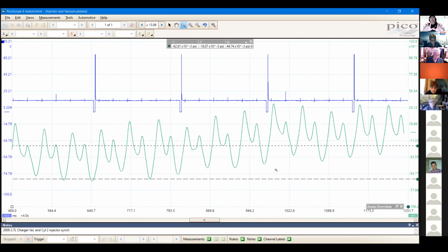And before you say it, and this is the last comment I'll leave you with, because I could talk about this for hours. Well, Adam, it's a Chrysler. If the cam and crank were out of sync, it wouldn't start. But this engine only has one cam sensor. It's only got one cam sensor on the driver's bank. Therefore, if the passenger's bank jumped, the computer is too dumb to realize it. He don't know. But that is another approach.